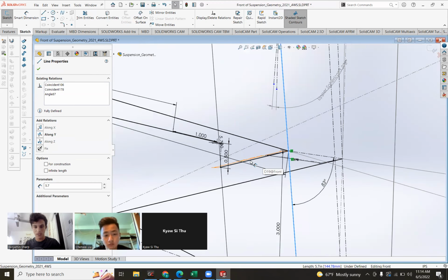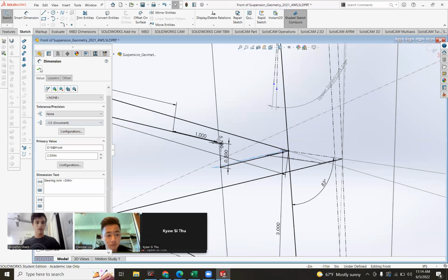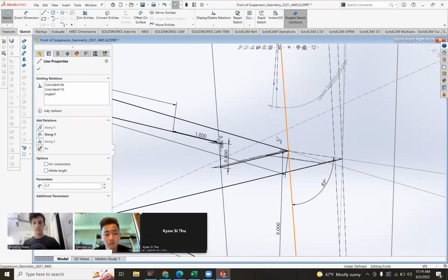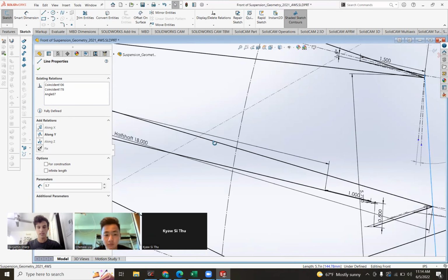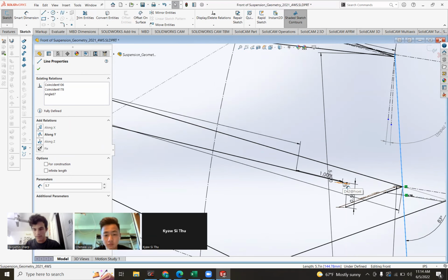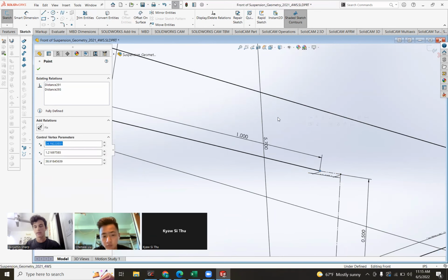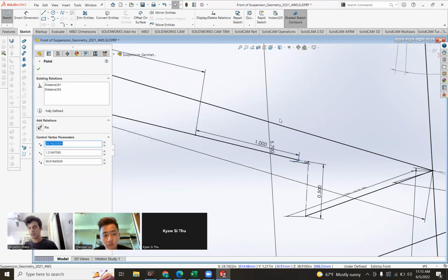And this line, along with this line, which is your steering arm, and I think it's named steering arm. Yeah, steering arm. So this line, which is the kingpin axis, connects those spherical bearings. This line, which is the steering arm, and this point right in here, those are exported into another sketch, and that's what defines the base of the knuckle.